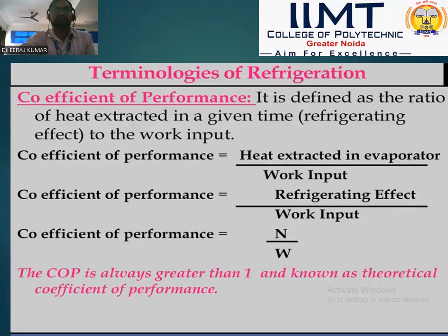COP. The full form of COP is coefficient of performance. Coefficient of performance is defined as the ratio of desired effect upon work input. In a refrigerator, the desired effect is the refrigeration effect, and in a heat pump the desired effect is the heating effect.